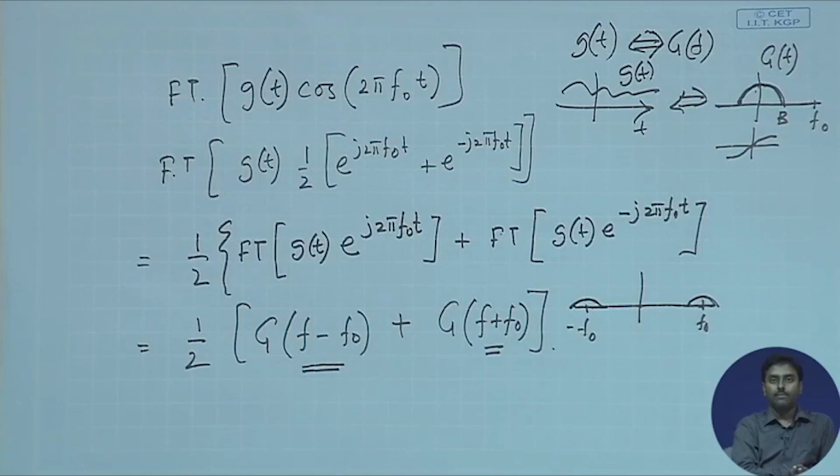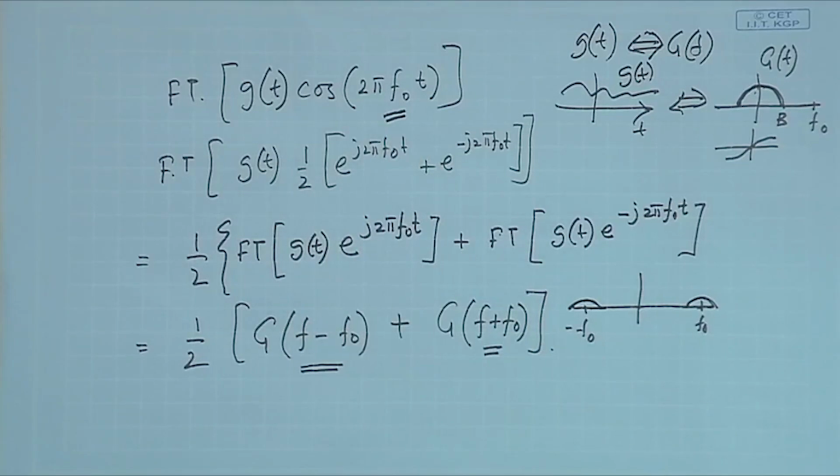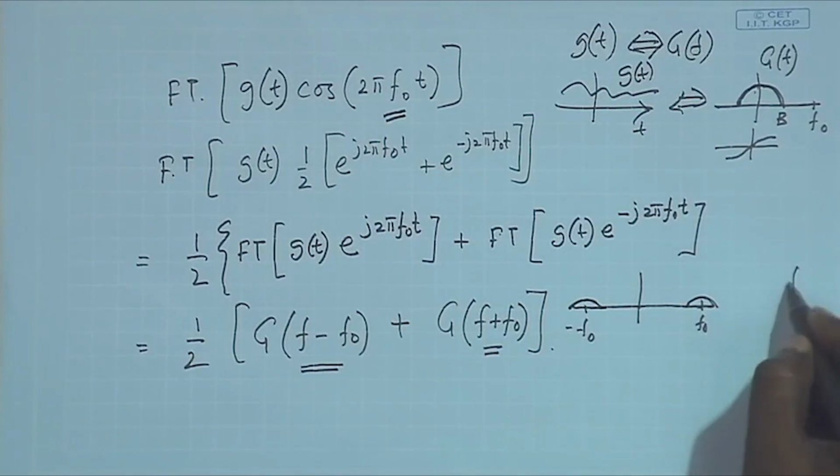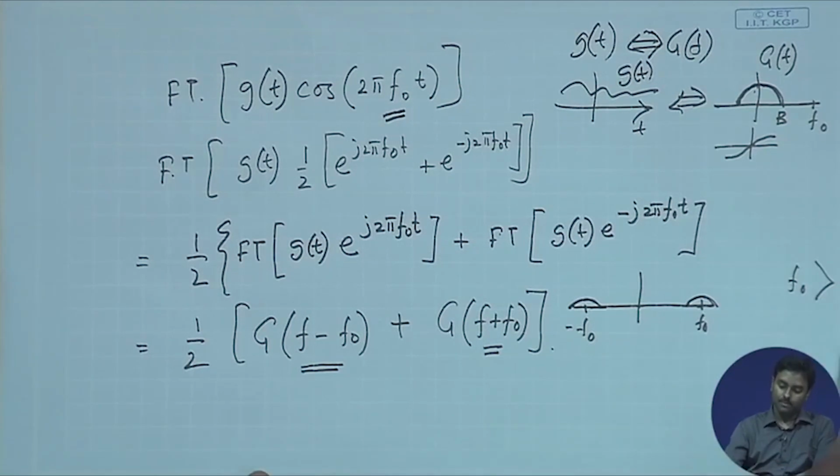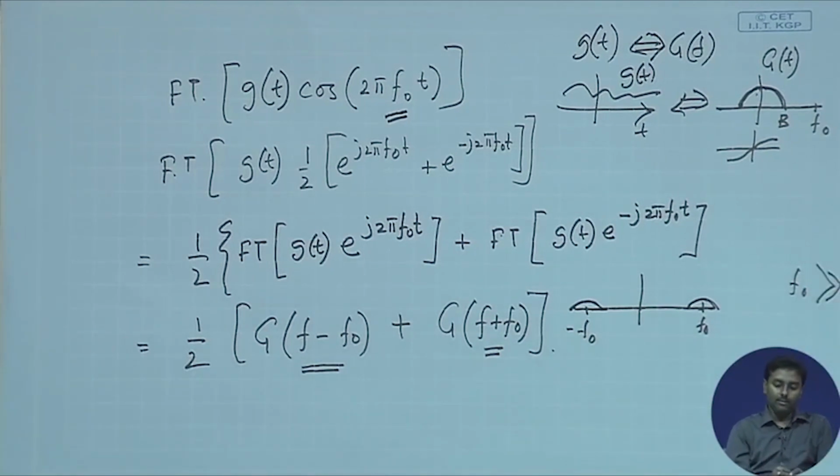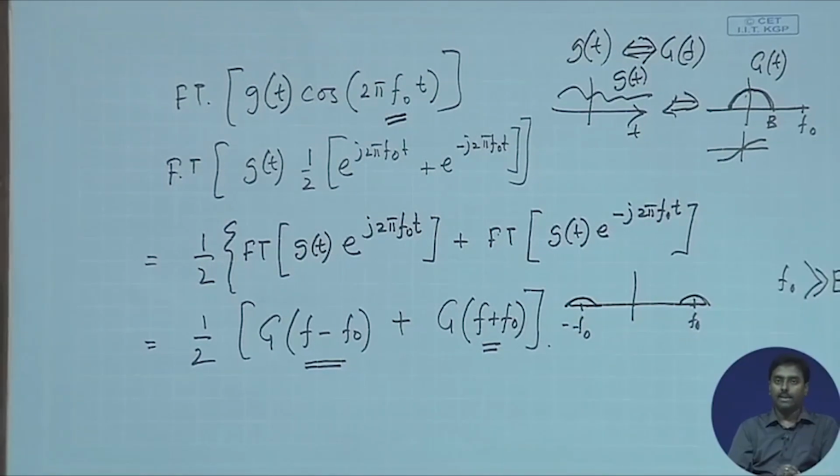So, if I represent the signal like a Fourier series or even a Fourier transform, I do not get any significant spectral component beyond this particular sinusoidal or exponential, whichever way I am representing. Okay. So, once the signal is band limited, if I multiply that signal with a real cosinusoidal signal of frequency f0, where I have deliberately put this f0 to be greater than b, or sometimes much greater than b, then this signal will get translated to that f0.